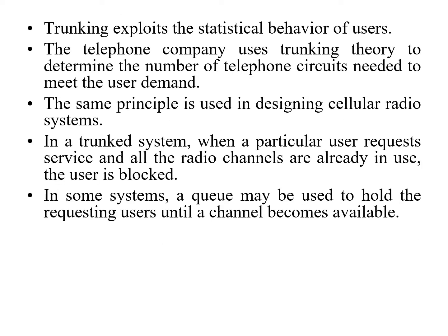Trunking exploits the statistical behavior of users. The telephone company uses trunking theory to determine the number of telephone circuits needed to meet the user demand. The same principle is used in designing cellular radio systems. In a trunk system, when a particular user requests service and all the radio channels are already in use, the user is blocked. In some systems, a queue may be used to hold the requesting users until a channel becomes available.